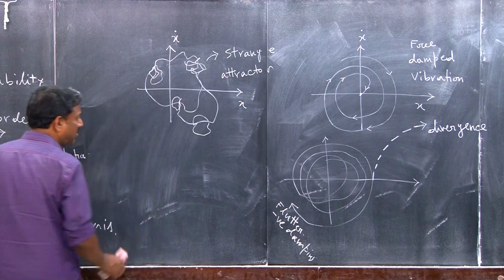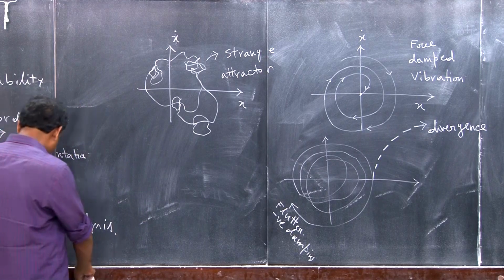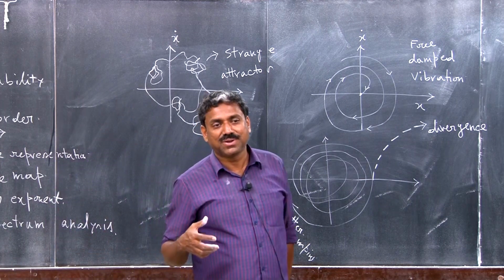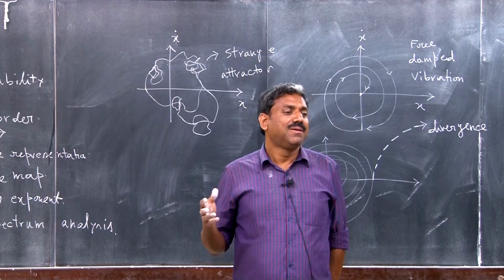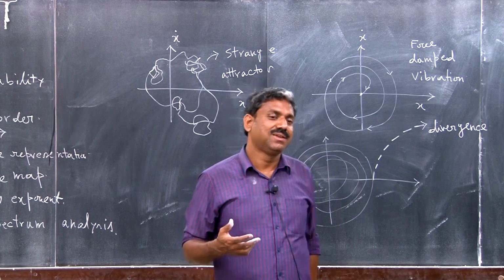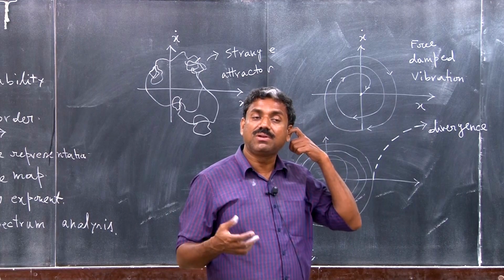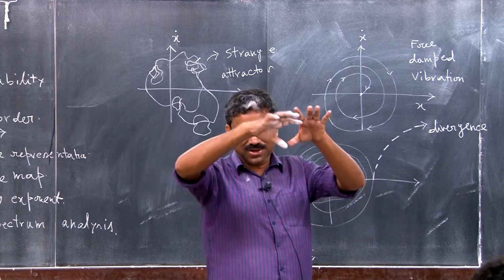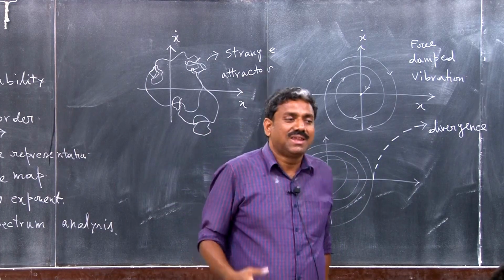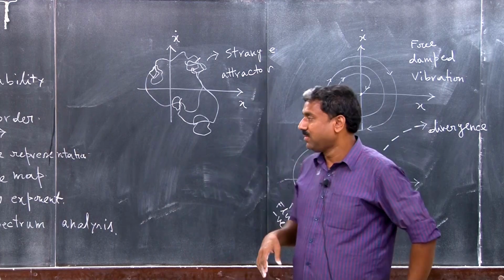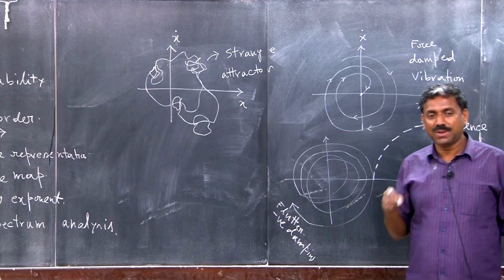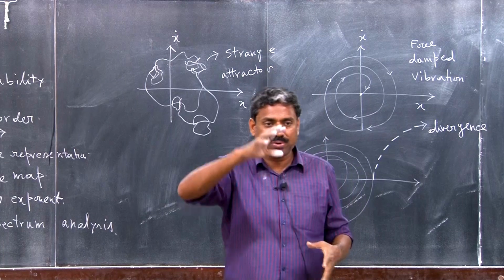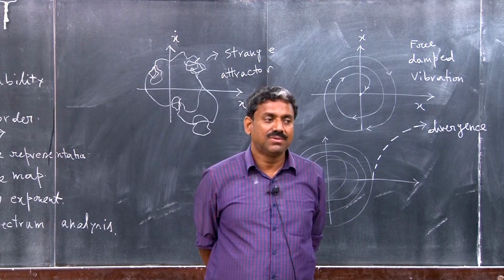For structural instability, let me tell you something. For a single degree of freedom system, you have a 2 dimensional space, but please consider that you have a multi degree of freedom system, with millions of degrees of freedom, right. So, you can have a reduced order model, but even if your reduced order model has 2-3 degrees of freedom, you will have a 6 dimensional space. Those are called hyperspace. And in hyperspace, it is not possible to measure all the responses. So, you have to construct this phase portrait using several algorithms.